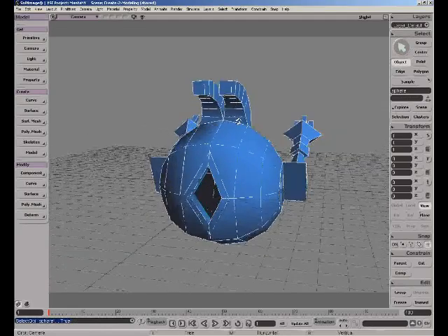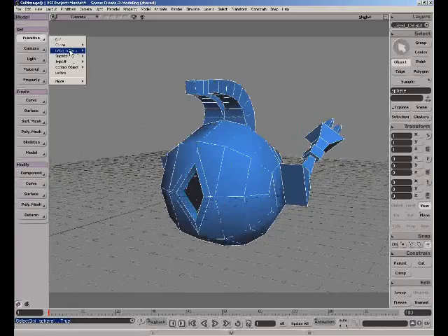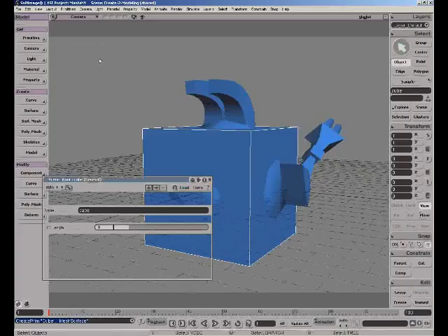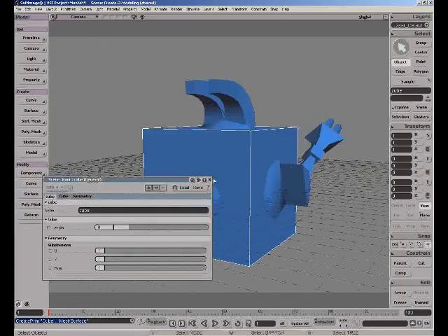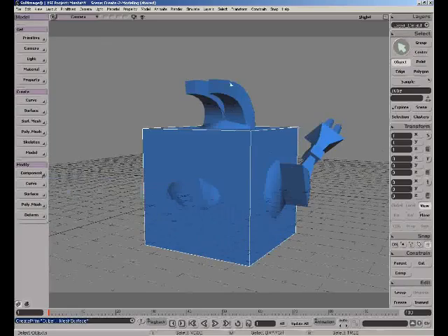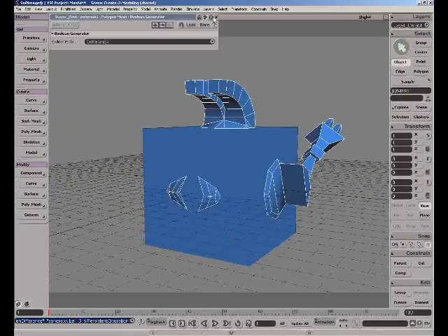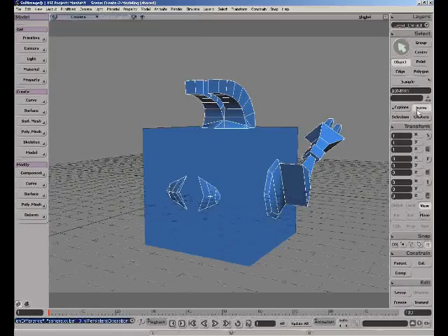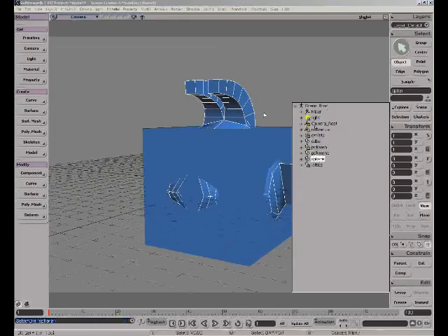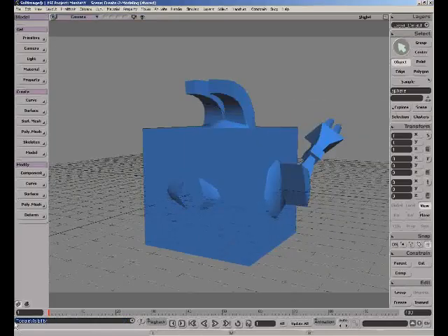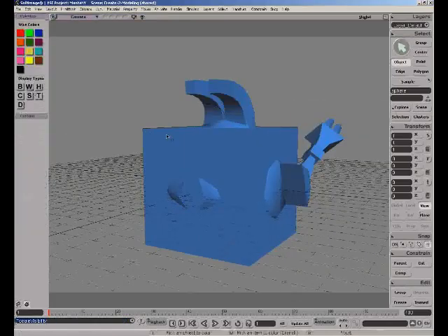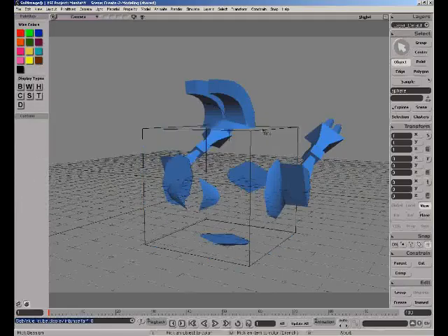Let's go ahead and do one more thing. We'll go ahead and grab a polygon cube, like so. We'll just position that right over top of our model, and we'll simply say we want to create a new polygon mesh using the Boolean tool. Click on like so, and we'll use the difference. Go into our scene selection, select our original object, hide that, and also go into a mixed viewing mode. We'll turn this into wireframe, and now you can see we've got a Boolean in here.